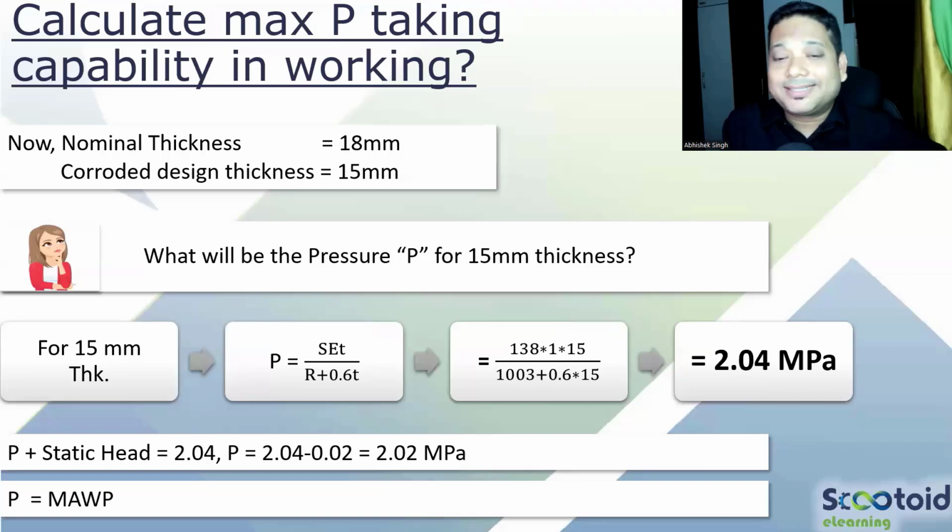So design pressure in new condition, basically. 138 is the allowable because it's considering a carbon steel. So allowable is not changing is what we are considering. But it may happen that your allowable may change. So remember that. But in this case, consider the same. If it is carbon steel material, 100 degrees Celsius, that allowable does not change. So we are taking advantage of that and we are using the same value. So give me the value. If I'm calculating MAP, allowable is 138, thickness is 18.